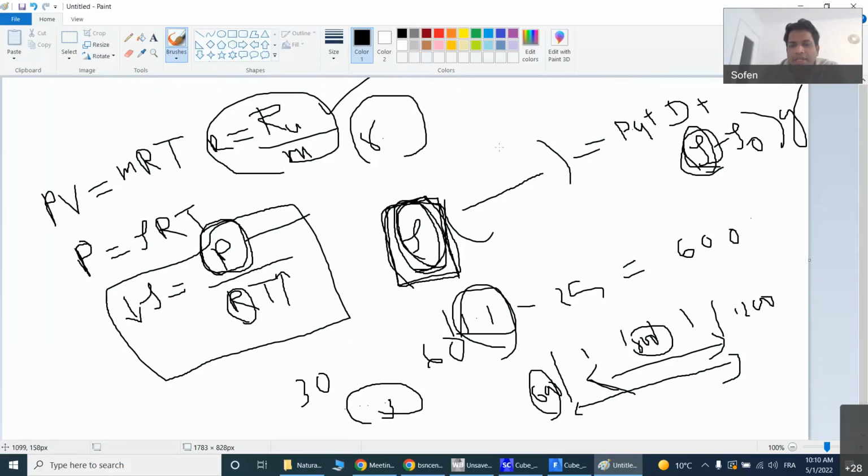You need to take care, otherwise your simulation will not give you a good result. To compute that, this is the variable density formulation, which is also known as the incompressible ideal gas formulation. At every point you need to calculate your density. That density goes into your momentum equation. Any difference in density with respect to the operating density gives you a buoyancy term, right? So this is the method.